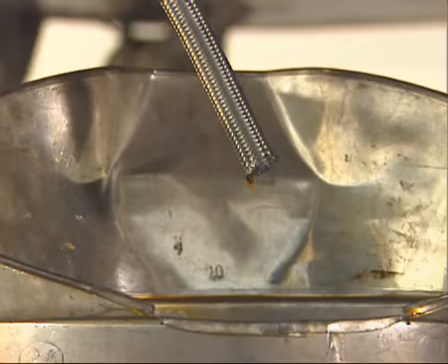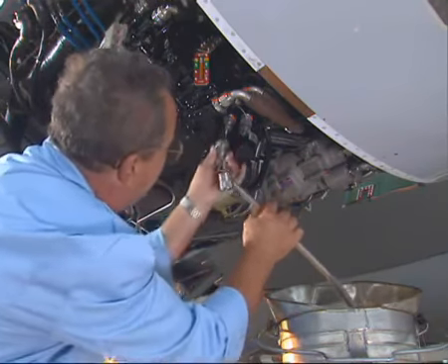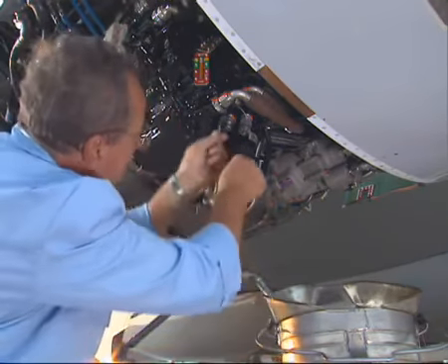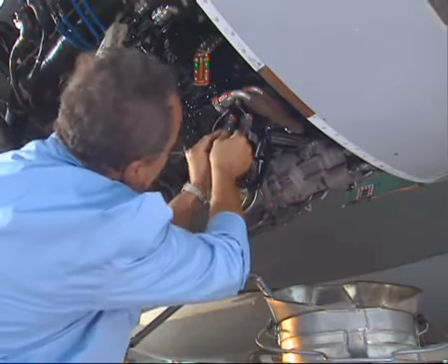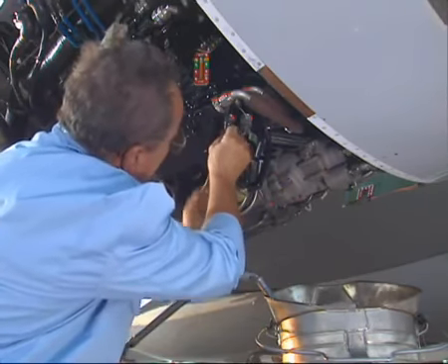When only drops of oil come out of the overflow drain hose, remove it. Install the dust cap on the overflow drain port.